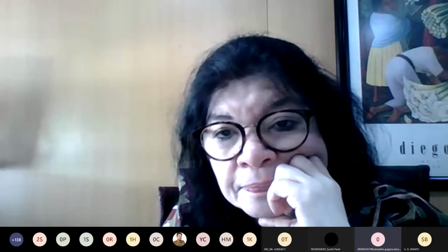So you are providing a damper at two-thirds height or whatever. Typically, dampers are 5% of your building weight, and you have it at the top, or at two-thirds height. So what is the question? I'm not sure I understand. Ma'am, wind dampers. Yes, for wind, this type of damper.